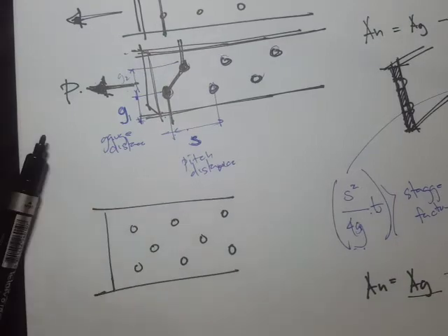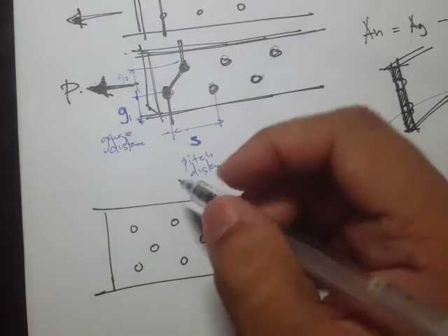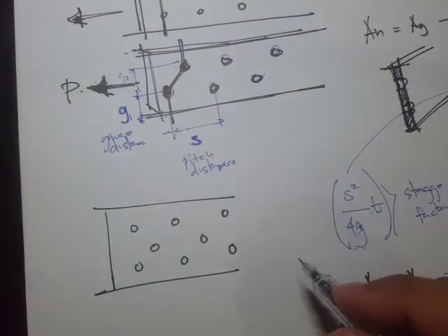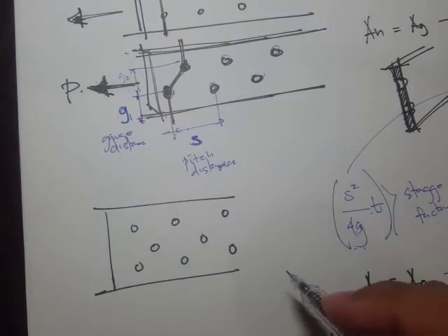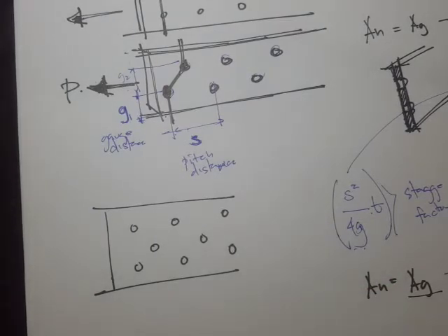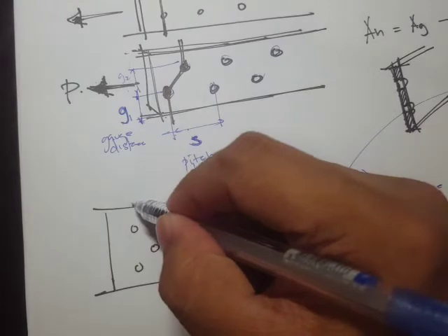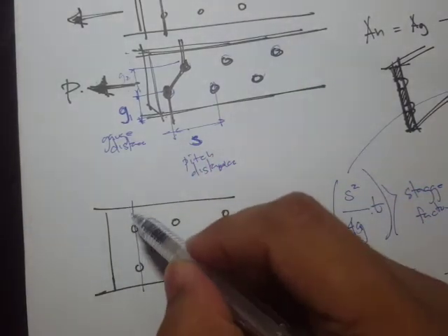Okay, so what's going to be the net area, let's say, of the failure path? Then it will produce multiple failure paths, and we have to evaluate those failure paths and solve for the minimum area, or the smallest area, because the smallest area would mean less capacity.